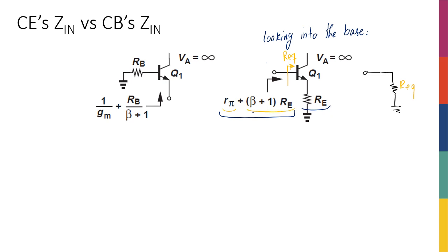And remember, all of this is small signal resistance. It doesn't mean that the transistor can actually, in reality, be replaced with an actual resistor, right? We are saying that in this small signal world, if we're only talking about little perturbations, then looking into the amplifier, the resistance that I'm going to see is this much.